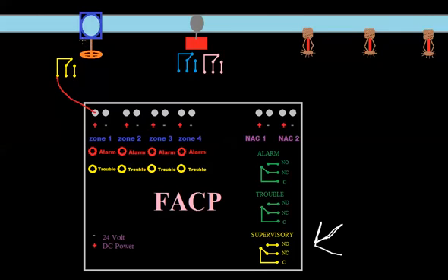I know I didn't draw one, but hopefully I've explained that well enough in the previous video so you understand that this would be internal on the device that monitors this valve. So now I'm just drawing it like a set of contacts because that's what would be on there. So now we have positive to common, and then we're going to go negative to normally open.